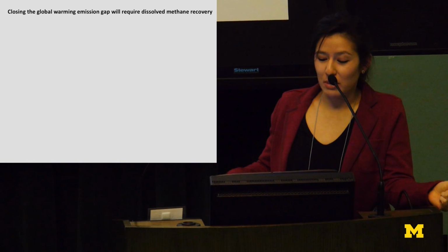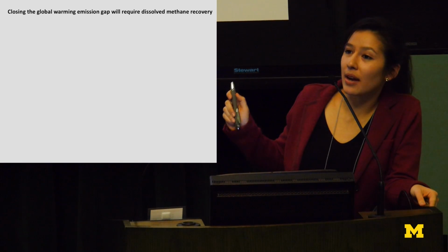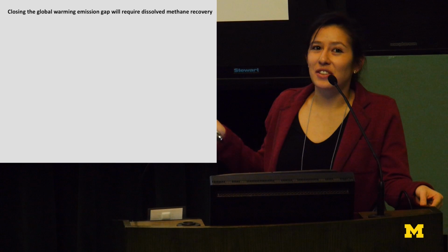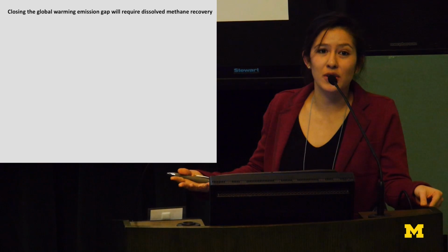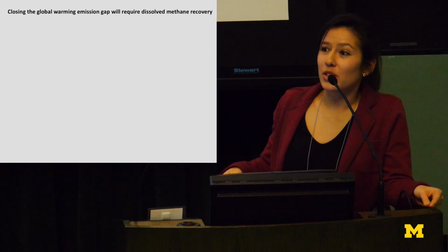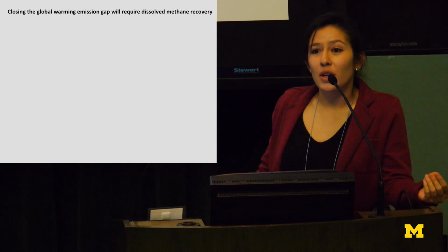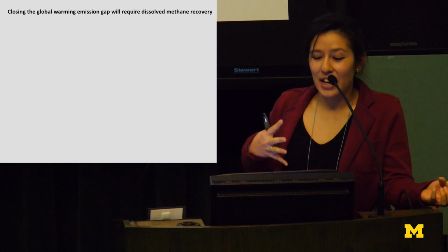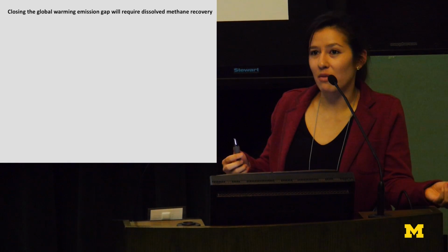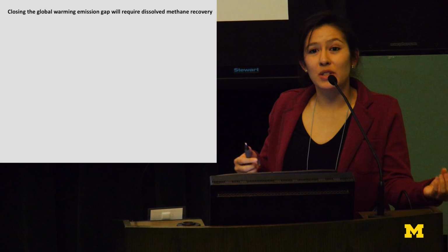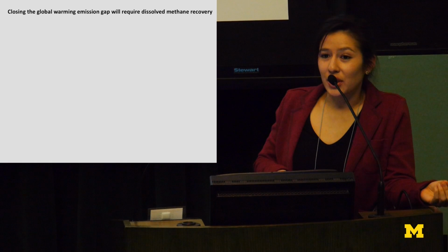Because it's an emerging technology, but we also see that there are disproportionately greater global warming impacts per energy use. And this is essentially just due to that dissolved methane present in the effluent, which we assume, if it's discharged to the environment, will be released. And so if we project into the future of where ANMBR could go as it goes to full scale, we'll see that it could approach this linear line between energy and global warming impact, and that's if that dissolved methane emissions are mitigated from being released to the environment, and as we improve the energy efficiency of